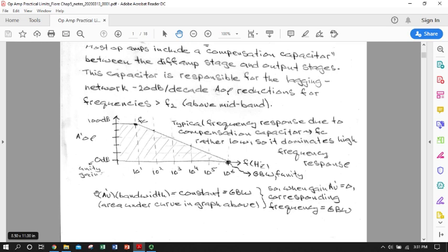So what this tells us is that for a real op amp, operating with a certain gain bandwidth, if we know what our actual gain is defined by our negative feedback network, and we look up our gain bandwidth product from our spec sheets, we immediately know the upper critical. We know the upper frequency limit of our midband region, and therefore we effectively know the bandwidth. And so we can use that when we're deciding how much gain we're going to get for a given input frequency signal. So we won't always be working with low frequencies.